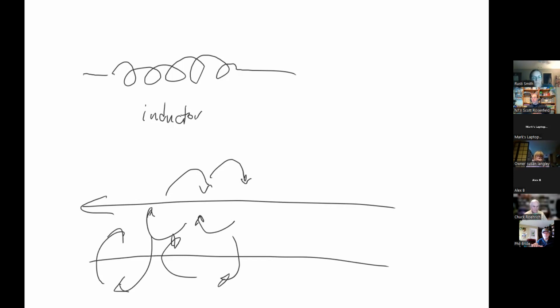It mimics it. Yeah, actually, if a current generates a magnetic field, the magnetic field that the second wire is in will actually generate a current. You'll have a current that is induced in the second wire. This is why two wires placed closely together, if they're not shielded from each other, can do things like crosstalk, because of the magnetic coupling between the two.